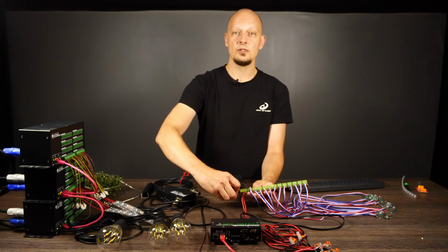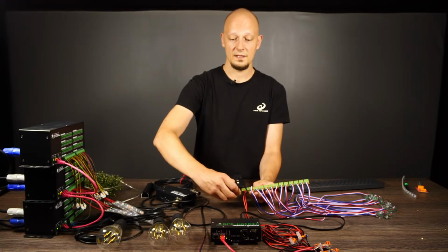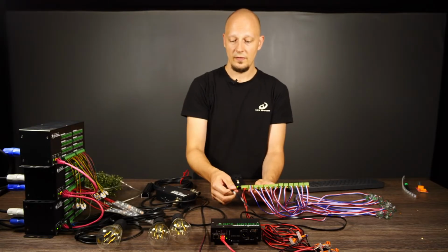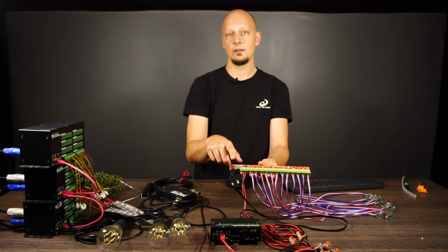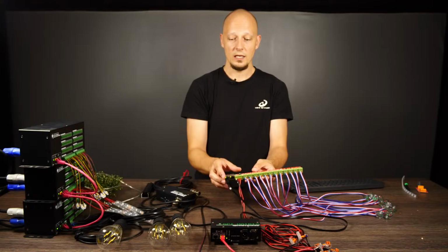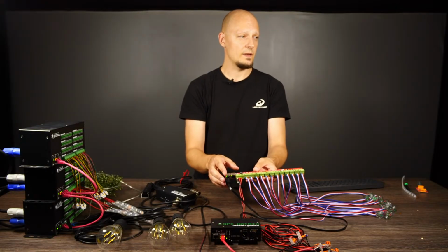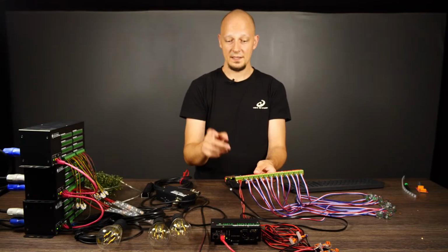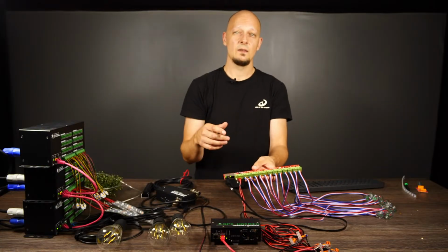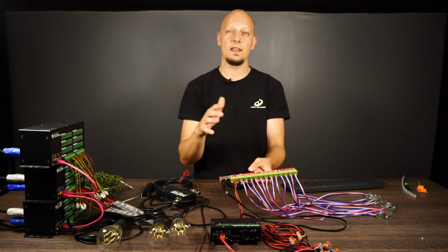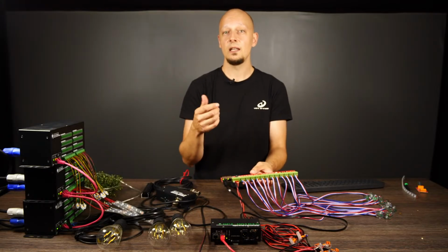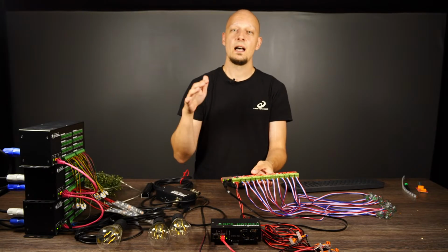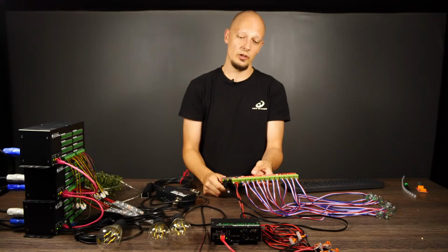The advantage is that you can send the signal over a long distance, up to 100 meters, with standard Cat5 cable, and you can daisy chain multiple pixel shifters in a row. In total, you can have, I think I have it here, 32 devices in a chain, and that will give you a total of 1,200 pixels. And that is the upper limit of a single output of the controller.